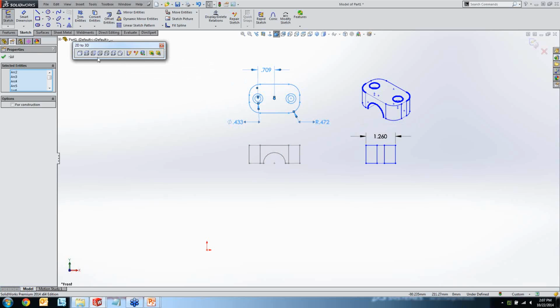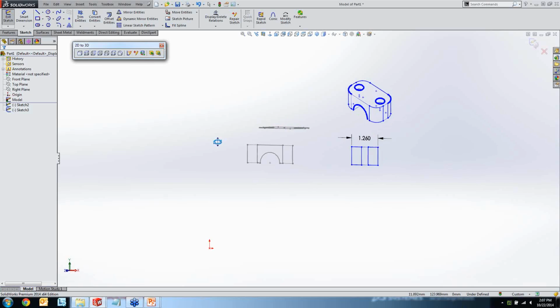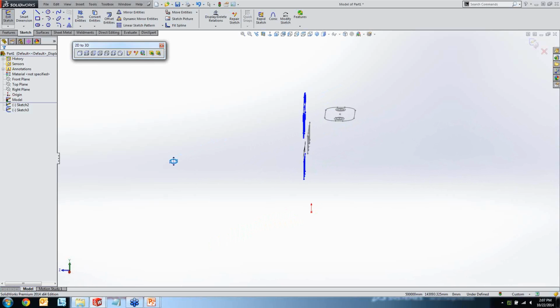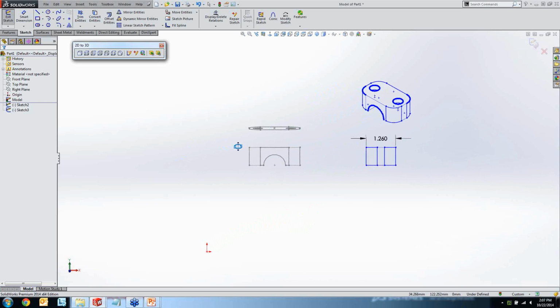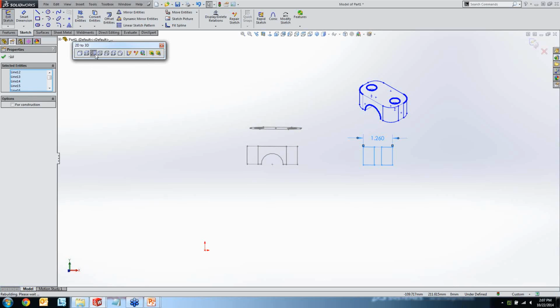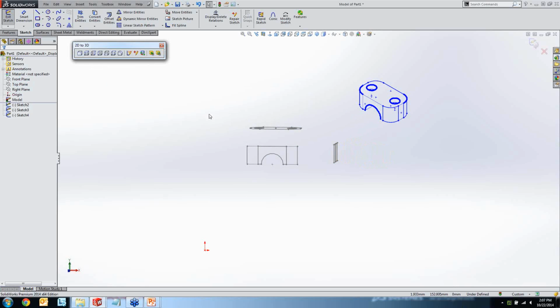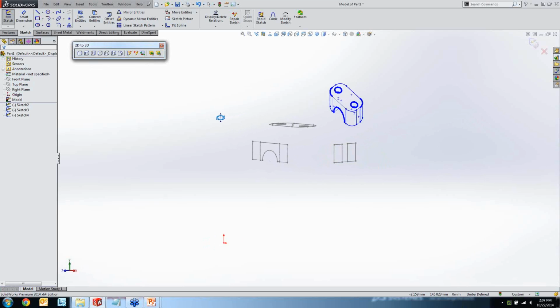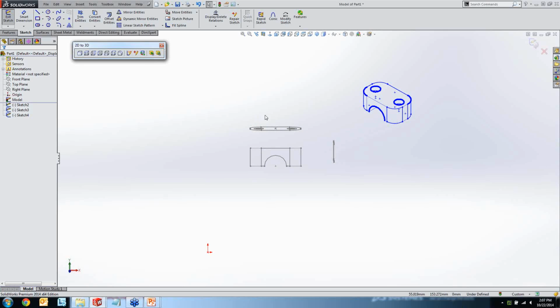As I highlighted the top view here, now I'm going to choose the option to add that to the top sketch, and you'll see that sketch actually rotate normal to. Now as I start to rotate the part around in 3D space, you can see it actually reoriented that part of the sketch. I'm also going to grab this area here, and I know that should be the right-hand view, so I'm going to add that to the right sketch. And again, just like the first version, that one rotated around to the side, so now I'm starting to get more of a 3D view. Now actually, this isometric view doesn't really need to be there, so I'm just going to highlight that and delete it.